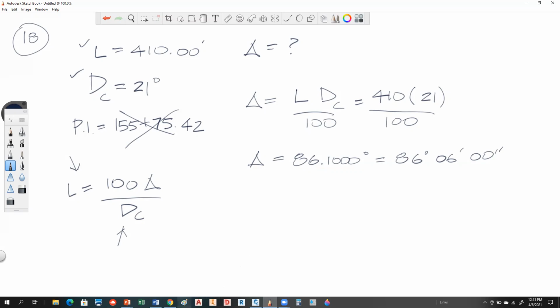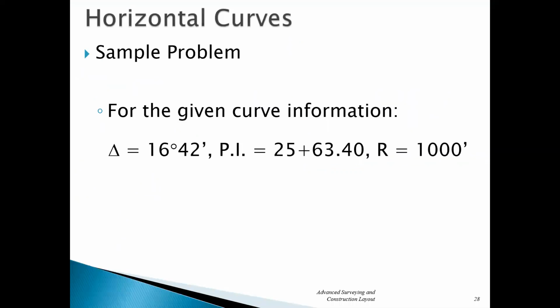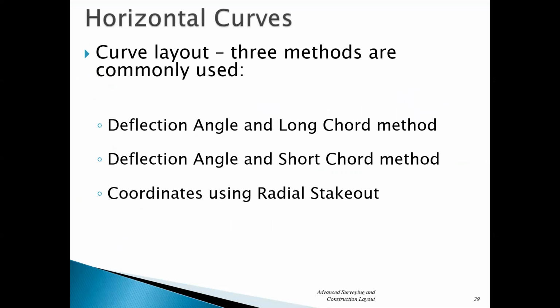All right, so let's go back to the PowerPoints. So we solved this stuff the other day. Okay, so this is what we were talking about. And Casey, this will get into your problem or question. For curve layout, you have different methodologies: deflection angle and long chord, deflection angle and short chord, and coordinates by radial stakeout, which is, by the way, what a lot of people use.